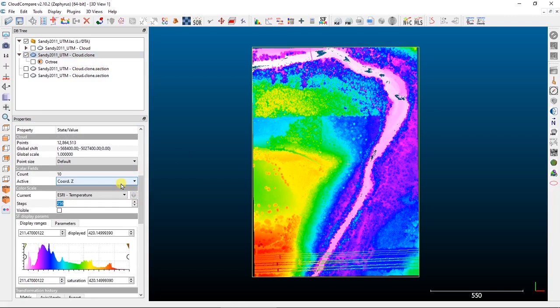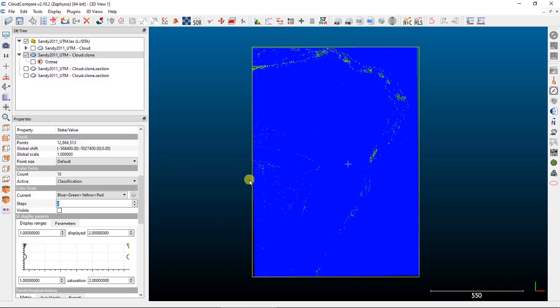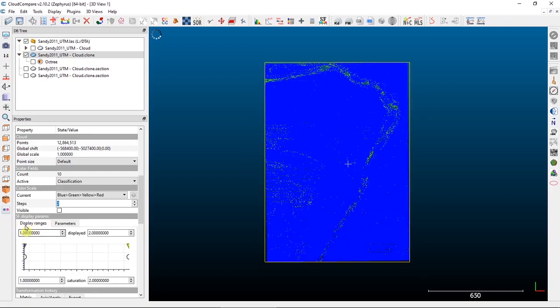In the last video, we looked at the classifications on this point cloud. So again, this one has a classification of 1 being unclassified and 2 being classified as the ground. In this case, if we wanted to extract out just the ground points from the rest of the data set, we can do that with a filter by scalar value selection.